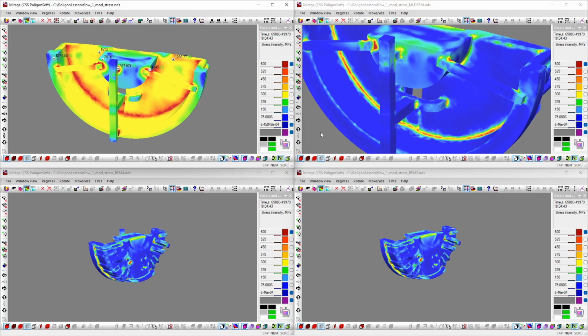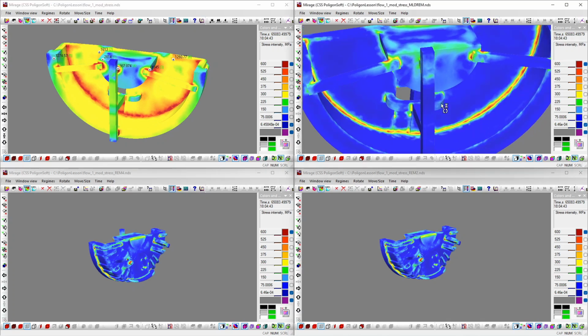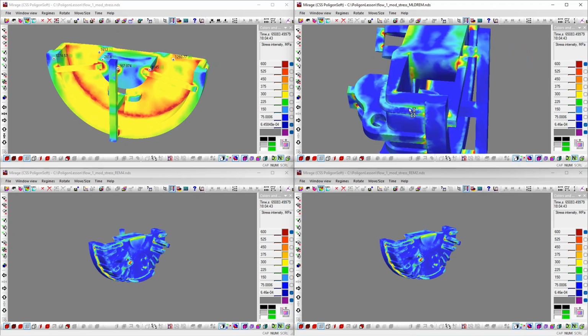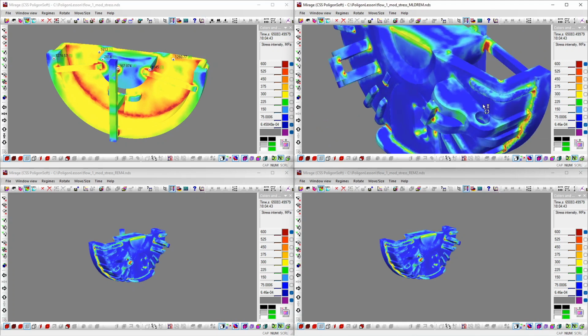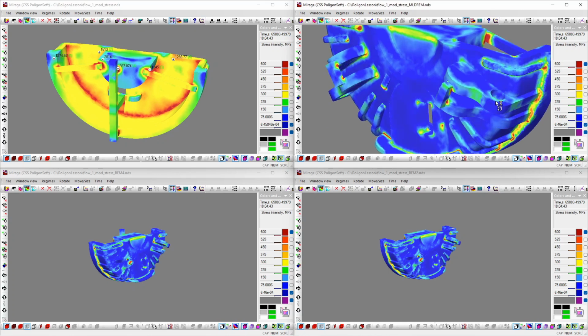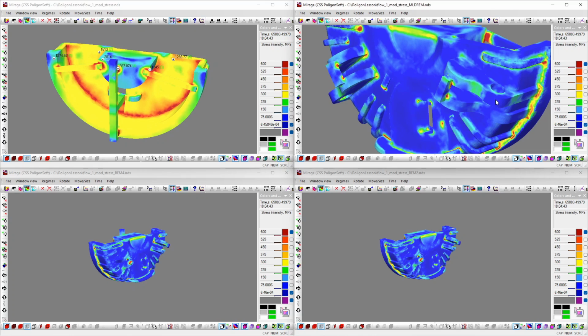In fact, only noticeable stresses remain in the areas where these stresses are caused by an unbalanced change in the geometry of the part itself. Here we must take into account that the calculation of the stress field before mold extraction was performed at 500 degrees, and the calculation when we extracted the part from the mold was performed at 200 degrees.